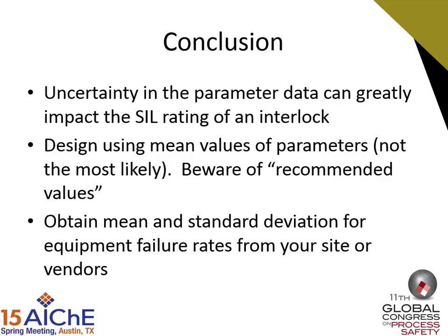The end result of all of this is that I should have convinced you by now that randomly pulling data out of tables, without understanding what those data are, is not a good thing to do. You need to really understand what's in there. The best data that you can get on the failure rates of your system, your gadgets, is based upon what goes on in your plant. If you have data based upon your plant, we can use that with some confidence. If you don't have data based upon what is in your plant and you're using generic data, now you need to do this with very great caution.